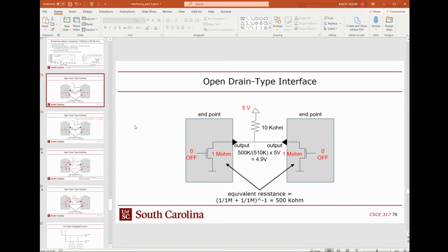So they have 2 wires per bit, and the reason is that the potential between those 2 wires can be positive to send a 1 and negative to send a 0, so they're sort of self-referencing. The other advantage is that any noise that affects one wire would affect both wires equally. So when you take the difference in voltage of those 2 wires, you cancel out the noise. It's called common mode noise rejection.